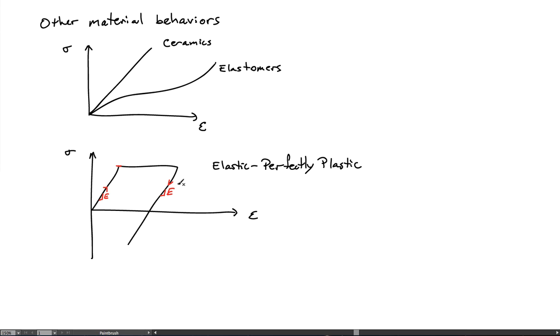I should mention with the ceramics, you have other phenomena. So for instance, the ceramic can fracture. When you apply deformation to ceramics, if you put too much tensile strain, so positive values of strain, onto the system, they'll likely fracture and break apart. Elastomers will do the same thing. If the strains get sufficiently large, they will also snap. Most materials will have that type of behavior.